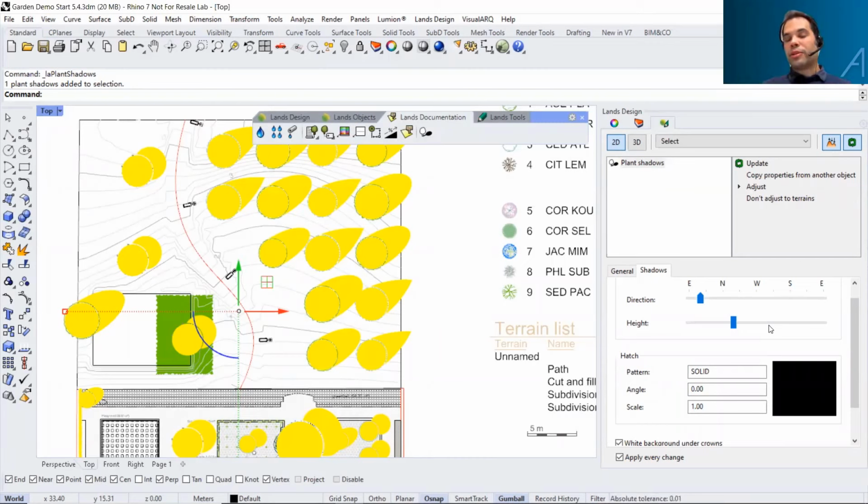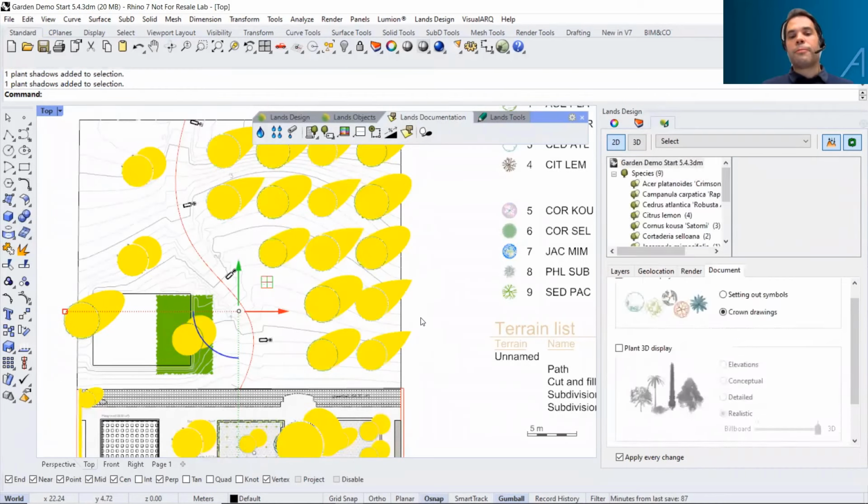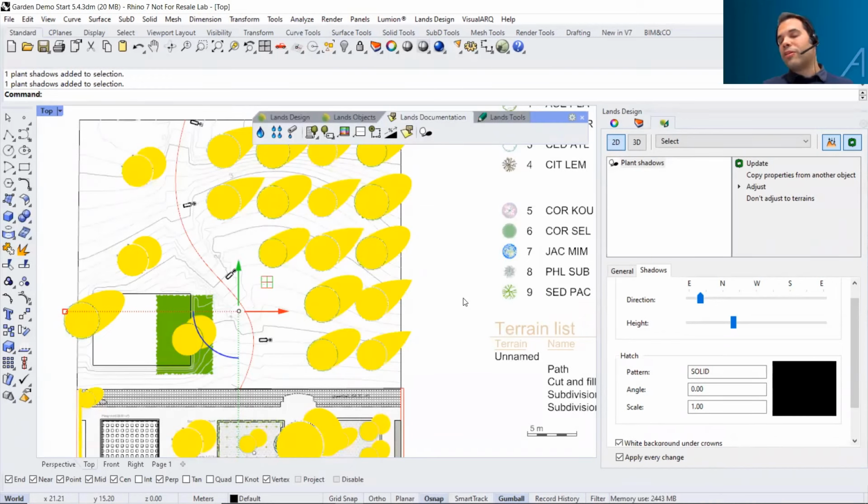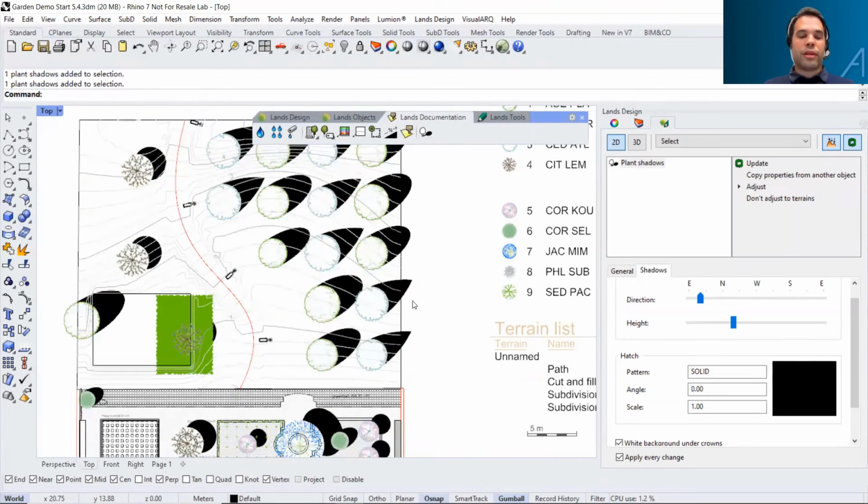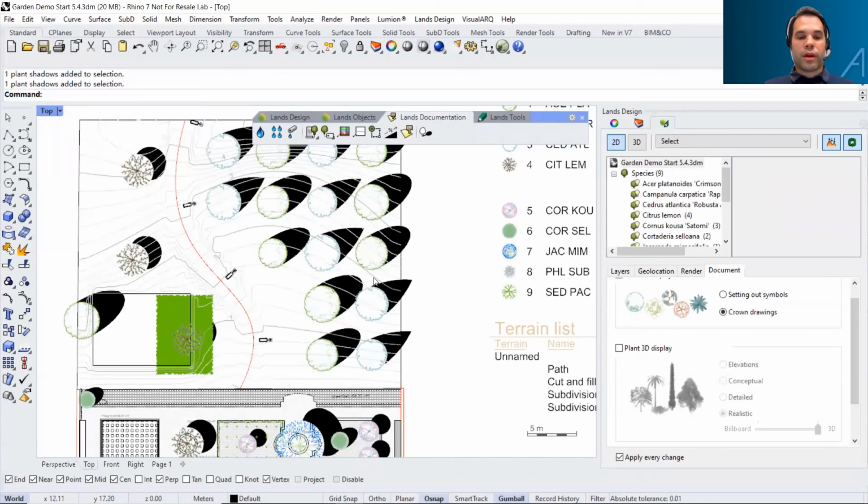Because Rhino provides an option to enable the sun, especially when using rendered mode and the lighting is using these rendering settings, we can simulate the kind of sun or shadow analysis along a day or along a year. These 2D shadows don't really link with this simulation, but this is used to have kind of 2D feedback of the plants and 2D representation of the model.